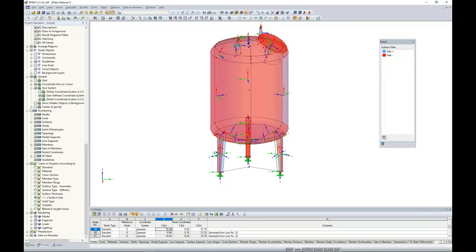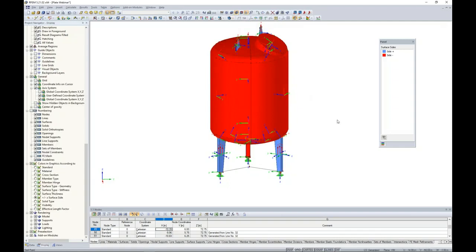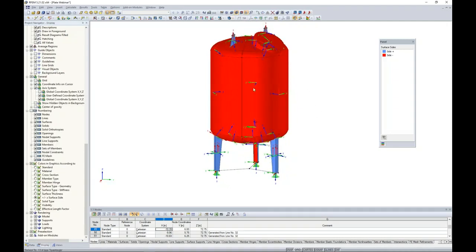But we also have the option to show the plus and minus Z sides of the surfaces. So when I go into a solid display of the model, all of the red surfaces have my Z negative pointing out toward me, essentially. We see the blue surfaces down here. That would just indicate the positive Z axis is pointing outward.